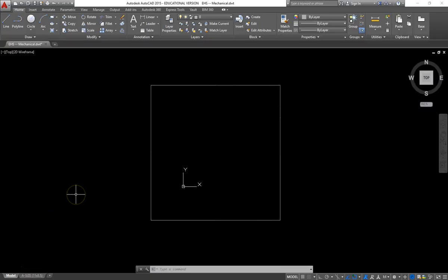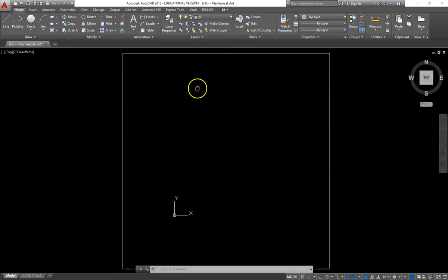We will be using our AutoCAD tutorial throughout this unit, and I will explain how to draw the guide plate, which is on page 1-18. You will see that the mechanical drawing template is chosen, and the mechanical drawing template has a square drawn in the model space. This square is so that you can load the file and have an appropriately sized drawing space.